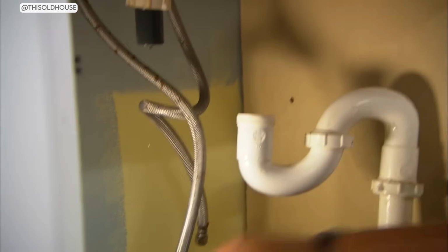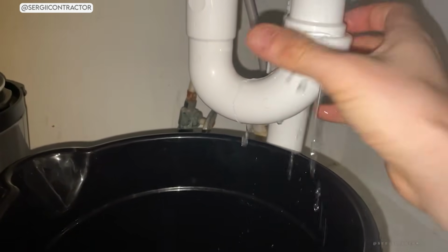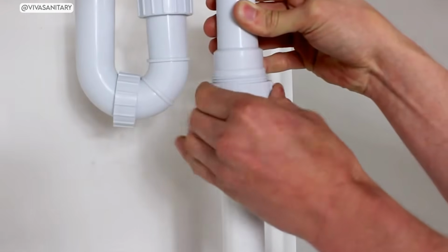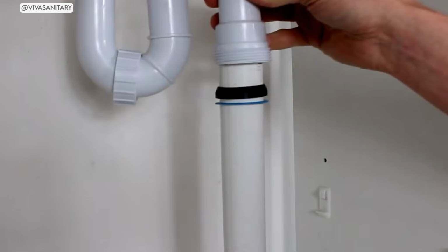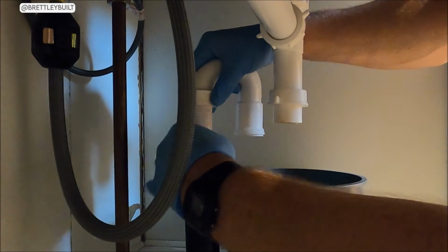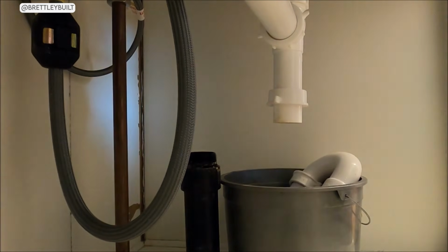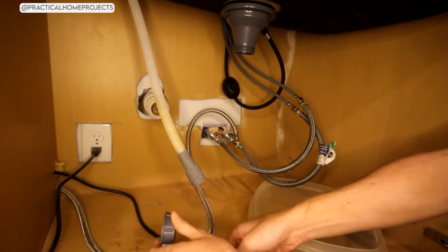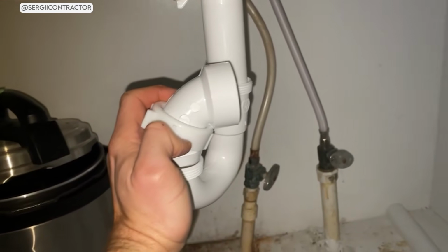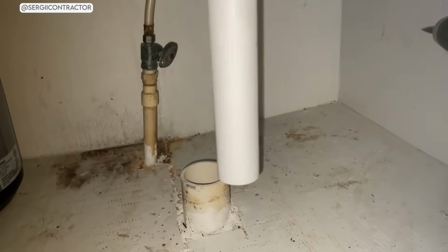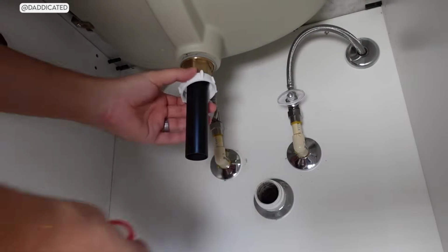The 10th and final item on our list is how to replace an S-trap with a P-trap. For many homeowners, this is a manageable DIY project, but it depends on your specific situation. If the drain line currently goes into the floor and there is no wall connection available, you will need to reroute the drain line into the wall and connect it to a properly vented sanitary T. In some cases, this means opening up the wall, adding a vent connection, and running new pipe. That can be a bigger project and may require a permit depending on your local jurisdiction.